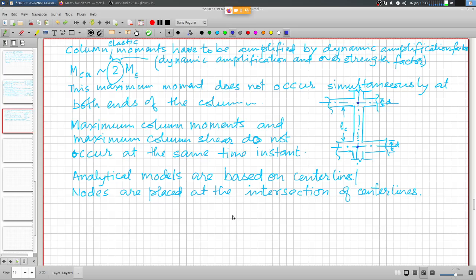While it's obviously deep within the beam column joint, while you are designing your column capacity at this level, at the face of the beam column joint, the column capacities and beam capacities are to be determined at this point, at the face.